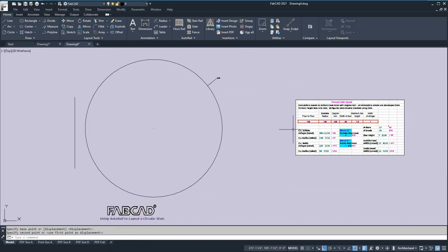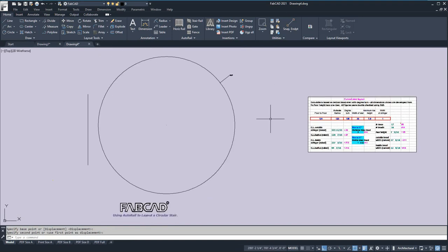Now we need to lay out the degree turn. So it's 135 degrees. So we'll start with a vertical line. First, we'll draw a line from the top quadrant to the center of the circle. And then we want to get to 135 degrees. We need to rotate this line, but I also want to copy it. So I'm going to click Rotate and select the objects, and then pick the end point, which will be the